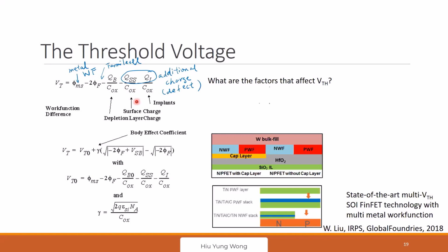Okay, so this is threshold voltage. Now then, threshold voltage is great, but we also have something called body effect. I just told you earlier, we can bias the body to change the threshold voltage. And basically, this VT0 here is actually quoted here again. This is the same equation as the above one.